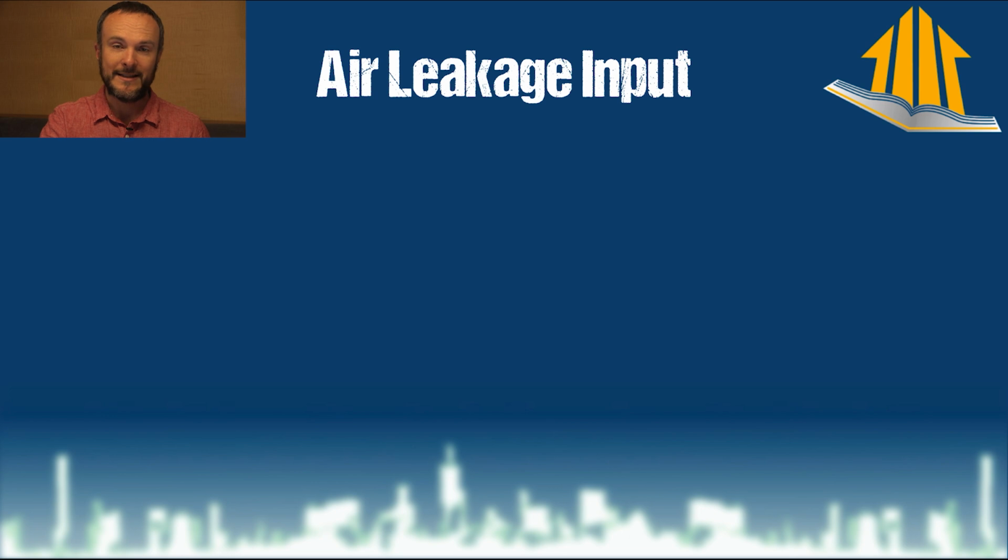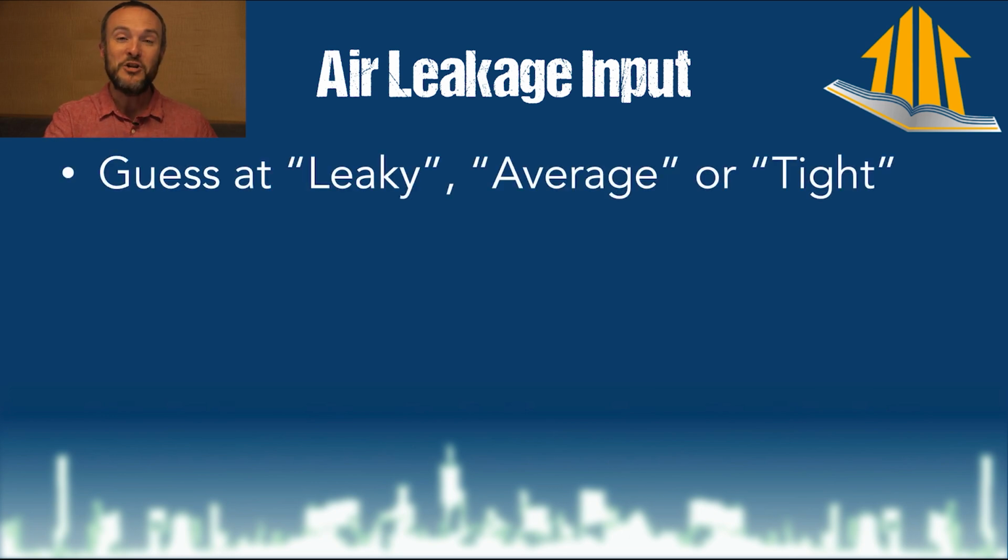So the air leakage is the last piece of this puzzle, and this is really important and really interesting. You have 3 options in most software. You could say that the house that you're modeling is leaky, it is average, or it is tight. I do blower door testing for a living. I have been in hundreds of homes checking out their air leakage. I have no idea what any of those words means, because average for what is the question. So don't use those inputs. If you're going to be using the software, just avoid those at all costs.